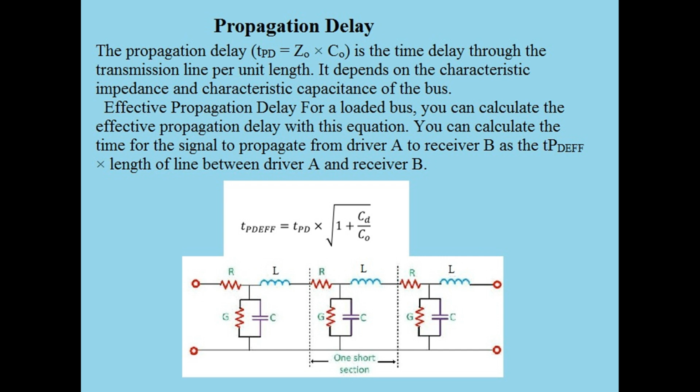Figure 3. Effective propagation delay for a loaded bus. You can calculate the effective propagation delay with this equation. You can calculate the time for the signal to propagate from driver A to receiver B as the TPD-EFF times the length of line between driver A and receiver B.